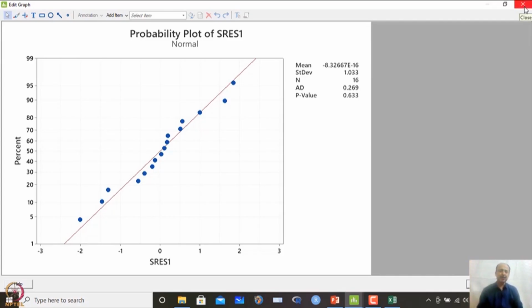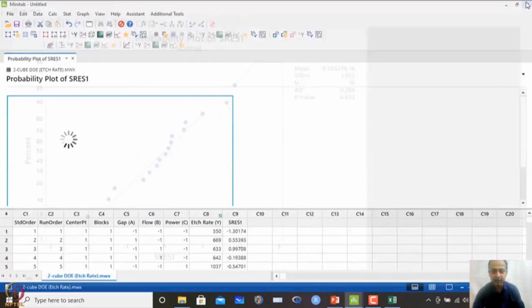Okay, but this is a preliminary experiment; we are trying to assess which factors are to be considered. This is not a complete optimization that we are doing over here, but if you think that a linear model is sufficient, and this is the working operating range of the process, then within this, the optimal condition is A at -1, C at +1, and B can be any level based on cost. So, that is the combination that we should look for.